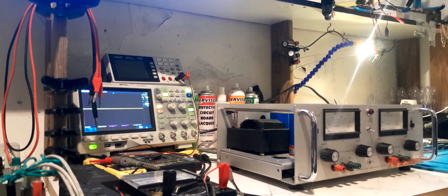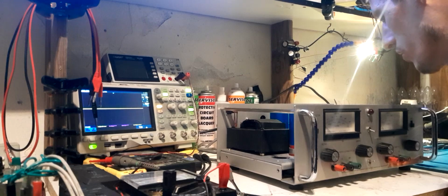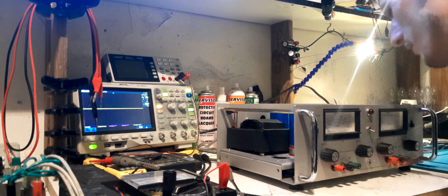I can't really say where we're going to start and where we're going to finish yet, because I honestly have not even fully worked out how this thing works yet. Like I said, obviously it's a power supply. Obviously one op-amp monitors voltage against a reference, the other one monitors current against a reference, but there's a total of 8 op-amps in there and 4 references. So for each channel there's 4 op-amps, and is it 4? 1, 2, 3, 4 on each channel.